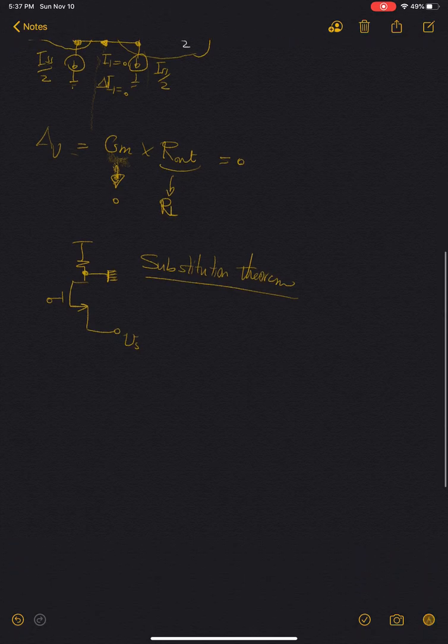So if we do that, for the small signal model of the transistor, we have an RO connected between drain and source of the amplifier. By connecting that node to ground, we basically add this R out to the output of the circuit, and as a result, the circuit can be simplified to this.